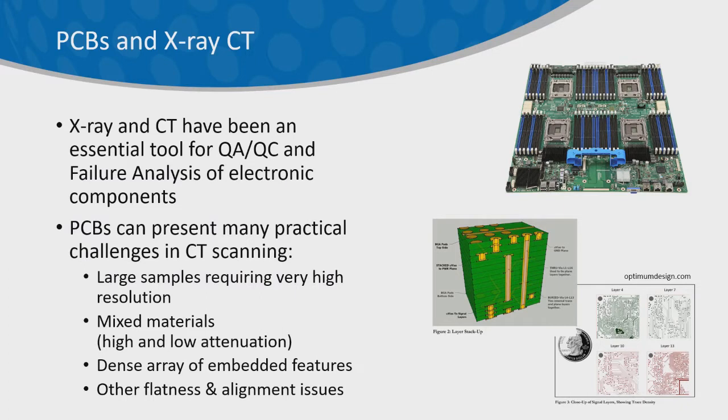And then one of the last things I'll say on this slide is when we're looking at even a large board, we take a motherboard and we're looking at 5-10 micron resolution. Typically, the first thing we always notice is that the board isn't flat. So when we're trying to slice through it, having the ability to what we call de-warp the board can become very, very important. And that's again, as you're getting higher resolution data out of these parts, something that we really want to pay attention to: our ability to de-warp the board, get everything on a flat plane so we can export that trace layer image we want. So there's a lot of work ongoing there to further streamline that process.